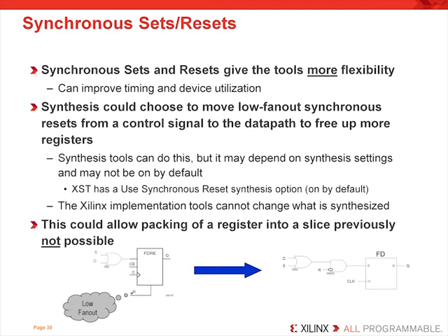Your synthesis tool should be able to do this, but it will depend on your synthesis settings and it may not be on by default. However, XST does use a synchronous reset synthesis option that is on by default. But note that the implementation tools cannot change what has been synthesized. So with whatever synthesis tool you have, its output is what you're going to be placing and routing.